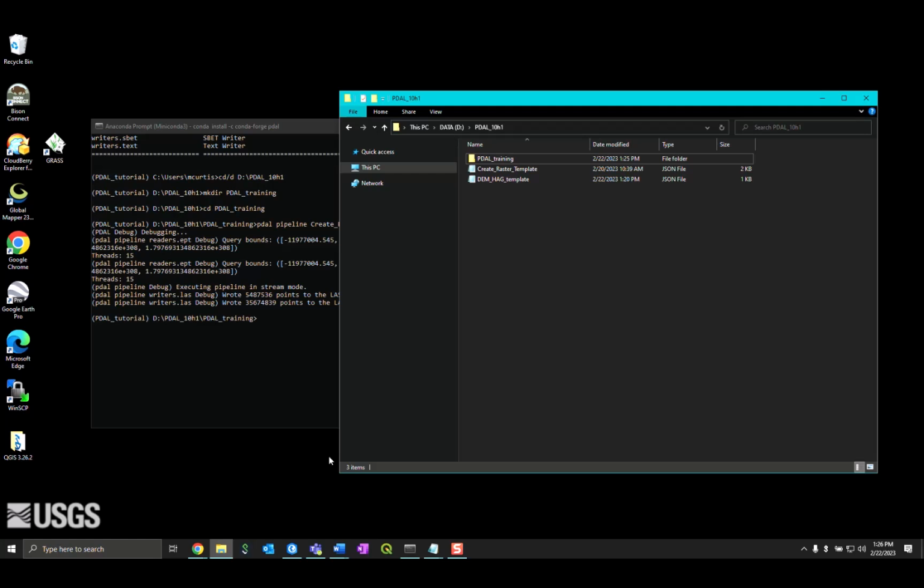Because we are using the LAS file format for point cloud data, various dimensions are stored as arrays in the data format, such as x, y, and z values. The filters.hag_delaunay PDAL filter adds a new dimension to the LAS file, which needs to be isolated and passed down to the next stage to generate the correct normalized height values in the raster.